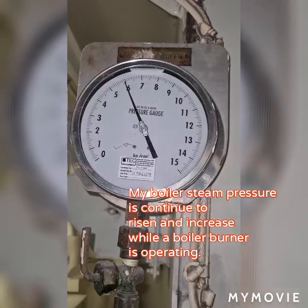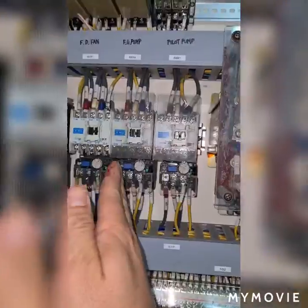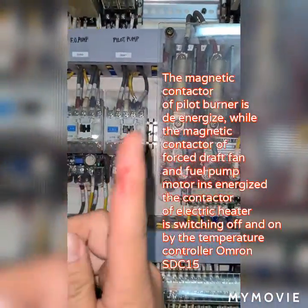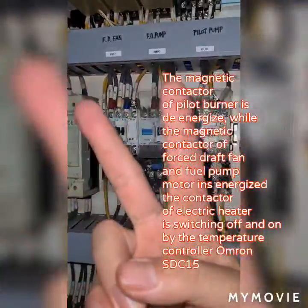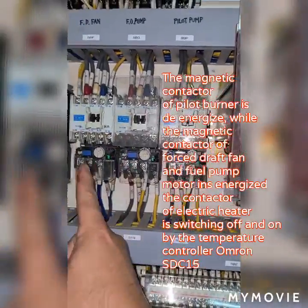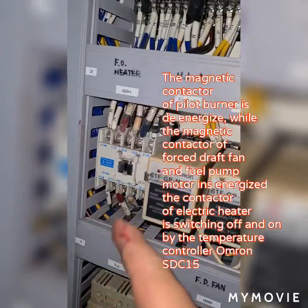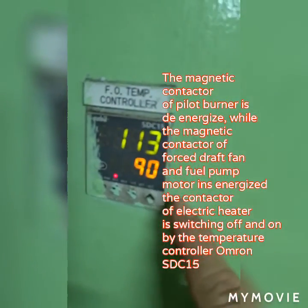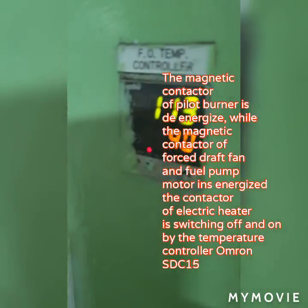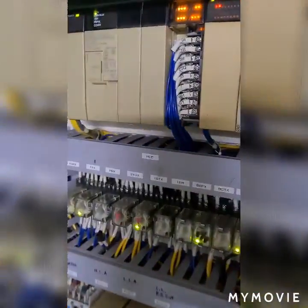My boiler steam pressure continues to rise and increase while the boiler burner is operating, and as you will see inside the control panel, I have the pilot burner energized, and the forced draft fan and fuel oil pump. Both of them are engaged and energized. While the burner is running, this electric heater relay will switch off and on by means of this temperature controller, Omron SD-C15.